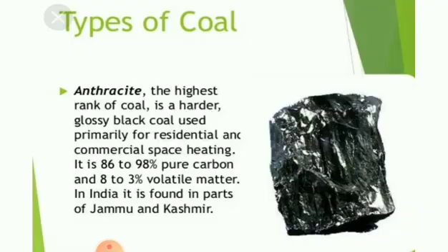Next, anthracite. Anthracite is the highest grade coal, right? It is lightweight and has the highest heat content. So this is the highest rank of coal. It is a harder, glossy black coal used primarily for residential and commercial space heating. The carbon content in this coal is 86 to 98%, right? And it has a heating value slightly higher than bituminous coal. It burns longer with more heat and less dust. It has 8 to 3% volatile matter. In India, it is found in parts of Jammu and Kashmir only.